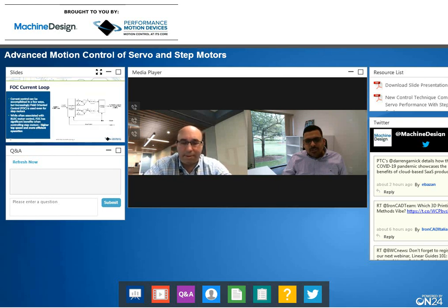Yeah, and what we wanted to talk about also, apart from closing the position with the encoder, is we do this FOC current control, and it lends itself to getting higher speed and a more efficient operation where you're operating in the sweet spot. So Ty, do you want to add anything on this slide? Yeah, I think you underplay the FOC part. So this is critical.